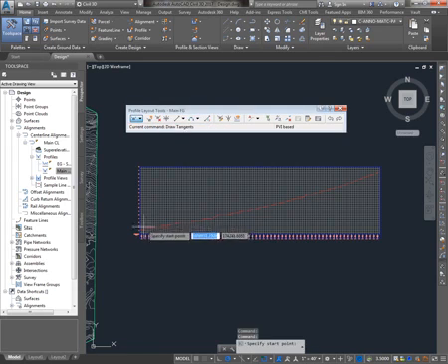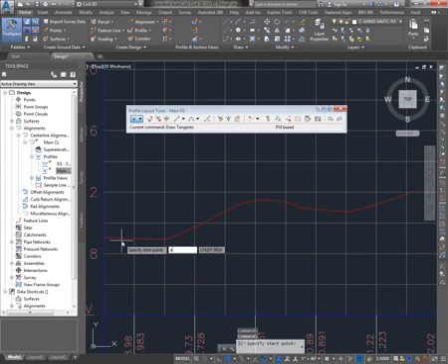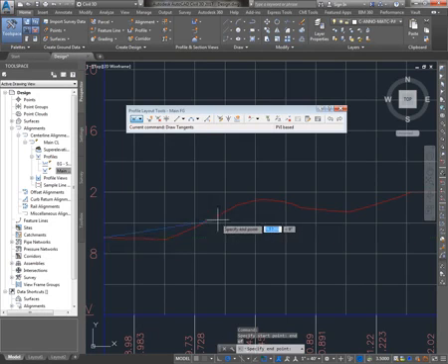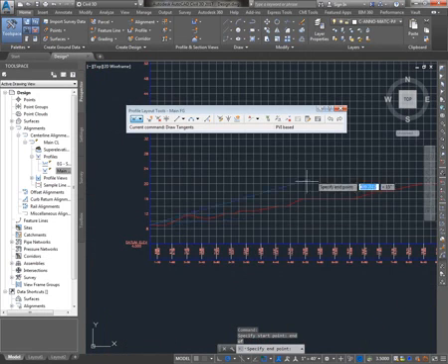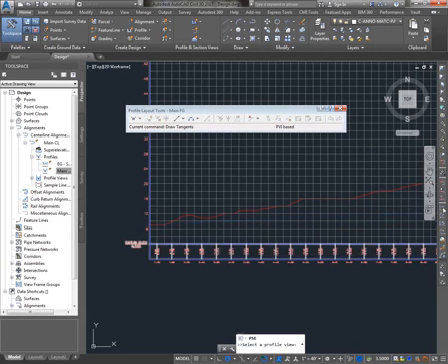I'll show you how we're going to use those. So I'll say I'm going to draw tangents, and let's say I'm going to conform at the beginning, so I'll just snap to the beginning of my existing ground profile. Now I could go click points, but it's going to be a little hard if it doesn't fall on a grid line and I want to set an elevation or something, and that's where these transparent commands come in. To use these transparent commands, what you'll do is start creating your profile, as I've done here, and then in the middle of that command I'll click Profile Station Elevation.